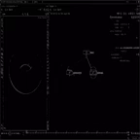And then you have these brown ports here, op input 1, 2, 3, and 4, referring to the 4 geometric input ports of the network here. So if I go up one level, you see I have 4 inputs here, and these 4 inputs are reflected here as brown ports named op input 1, 2, 3, and 4. And I think I missed primnum. Primnum is the index of the currently processed primitive, in case of a primitive VOP.